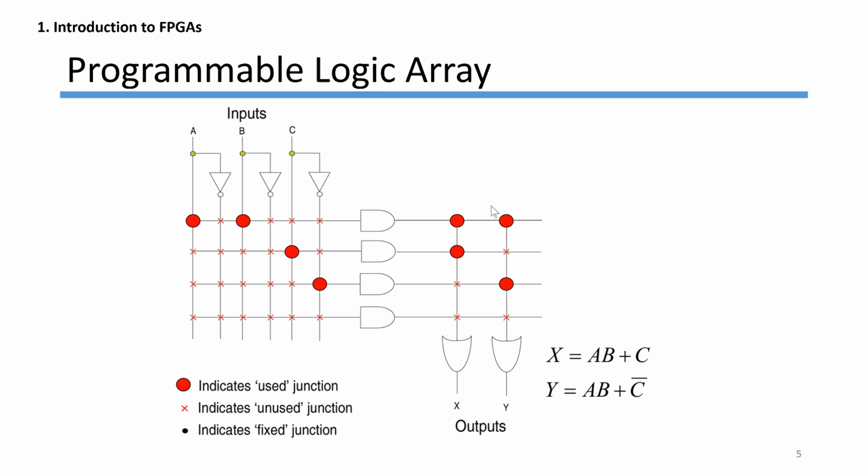So it is A and not B. Programmable logic can then be extended into programmable logic arrays, as you can see here. Now, instead of just having multiple input AND gates, the outputs are based on AND gates and OR gates. So the gates just before your outputs down here are OR gates, and these along here are your AND gates.